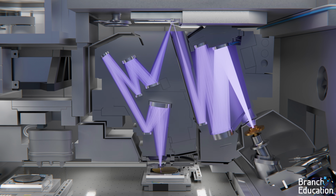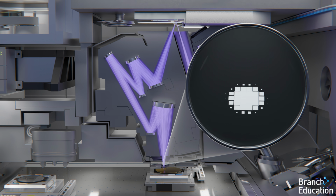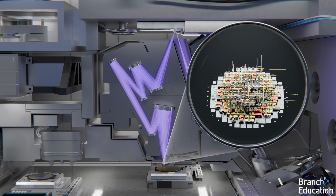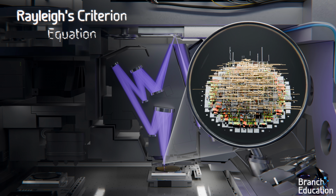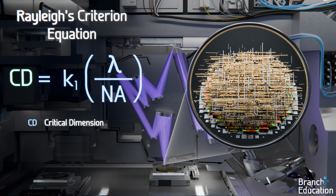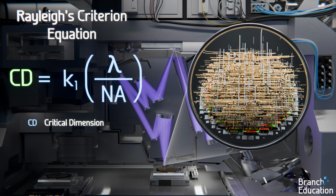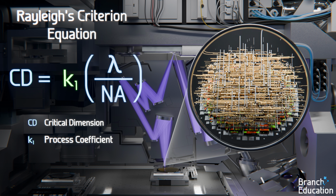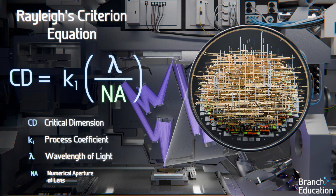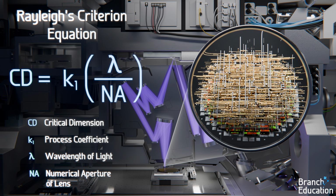To understand the projection optics, we have to discuss what determines exactly how small these wires can be, and for this, Rayleigh's Criterion equation is used. This equation states that the smallest dimension, or critical dimension, is equal to K1 times the wavelength of light, or lambda, divided by the numerical aperture, or NA.